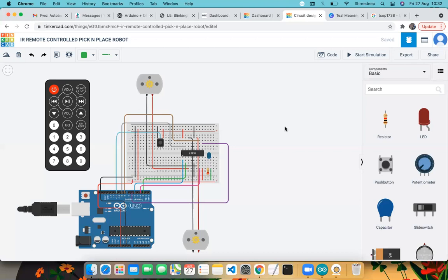This frequency is not visible and not audible. If I talk at 98.3 megahertz, you can't hear it, and probably I won't even be able to talk at that frequency. So these are not in the audible range, but they provide an upward frequency translation from the lower frequency to the higher frequency. And the advantage is twofold.